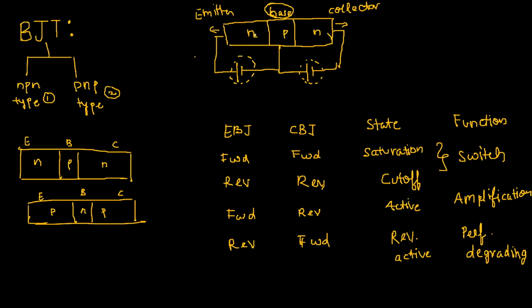The N region on the left is called the emitter, and the one on the right is called the collector, and the thin region in the middle, which is differently doped, is called your base. The basics of this is that your emitter is extremely heavily doped, your collector is mediumly doped, and your base is very lightly doped. We do not really have to get into the physics of how this works. We'll explain that in different lectures later on when there is a necessity for it.